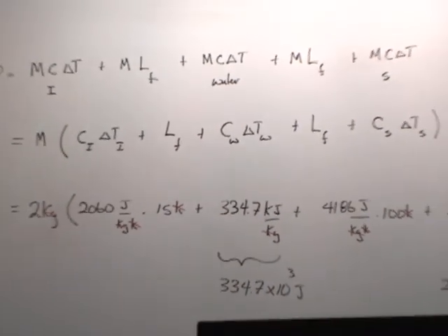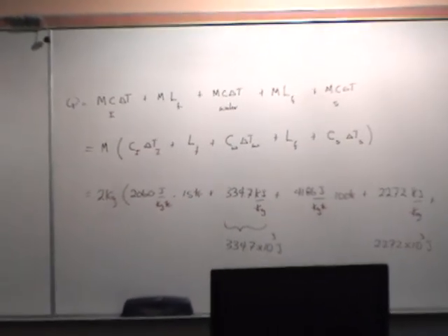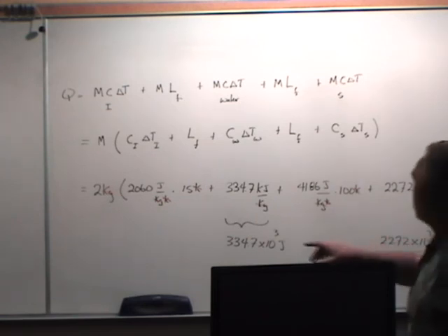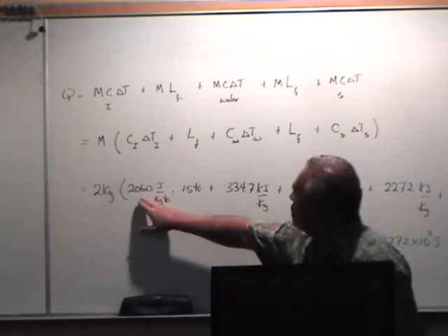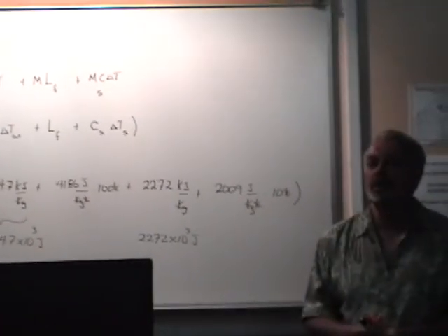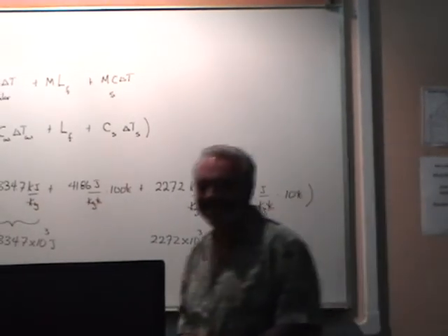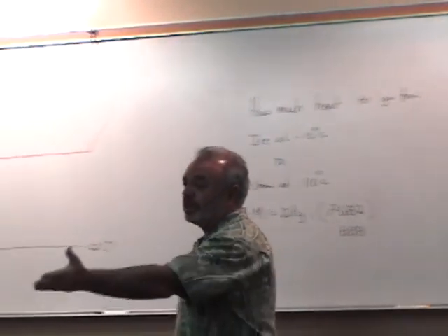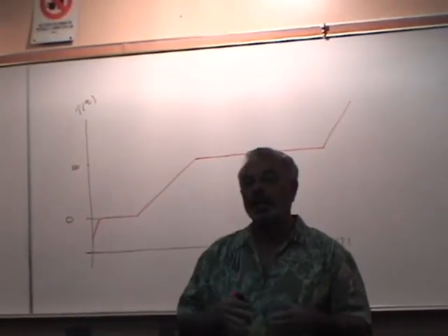Christine? Does the specific heat depend on temperature? Actually, yes, it does, but we're not going to take into account the specific details of the specific heats. We're just going to take these numbers as averages. We're going to assume it stays constant because it changes so very little. You just put it down as it comes out of the book, as a number in the table.